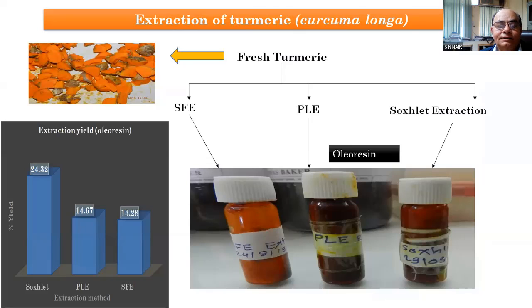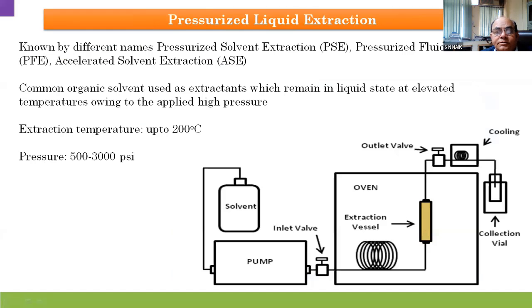Then you can see the solvent extraction, the supercritical extraction using a co-solvent, because in Brazil and elsewhere they use carbon dioxide and alcohol to isolate the total extract, but it requires very high pressure. For industrial scale, it is not feasible. So because of that, we take the essential oil first by liquid carbon dioxide, then you crystallize that extract to produce curcumin.